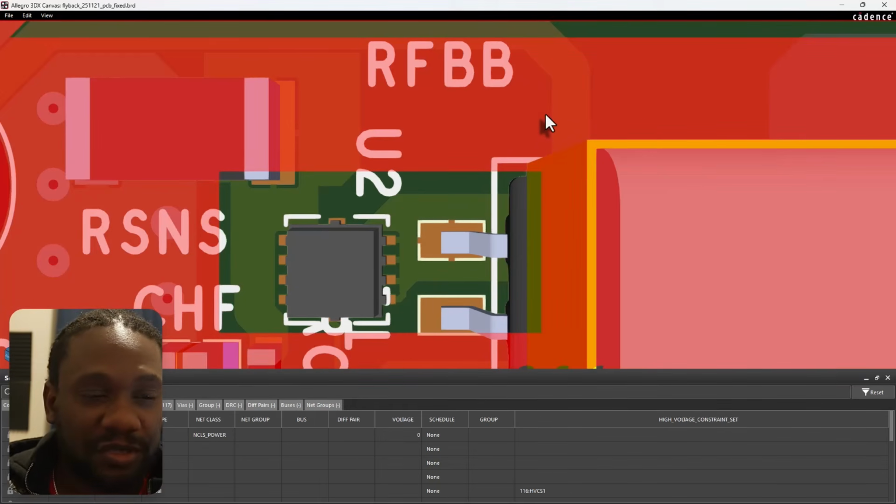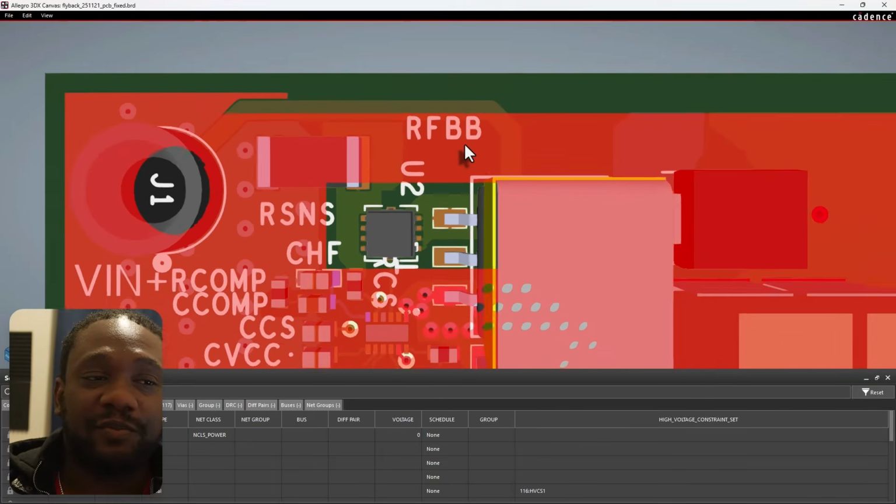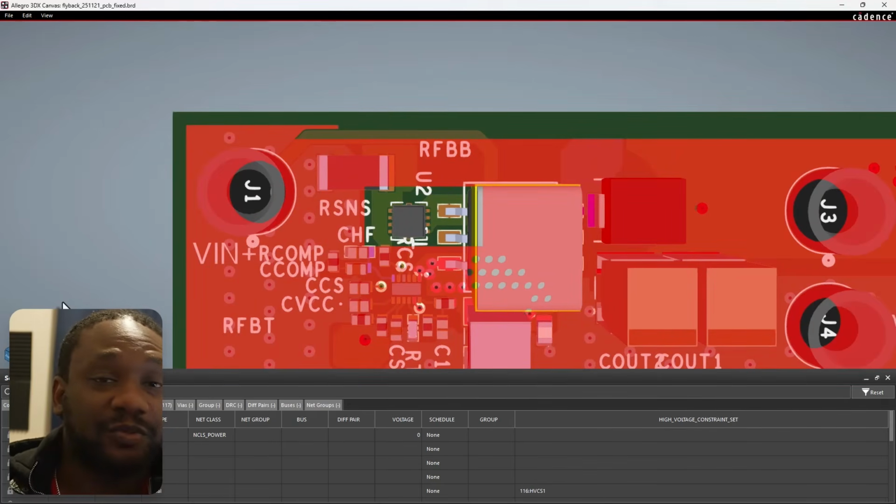So it's a bit nuanced, but it's a doubly effective method when you're playing with inductances and capacitances to lower that impedance. Because the lower impedance, again, is what the field is looking for, not necessarily the shortest distance in space. All right, so just a quick recap. We highlighted the two hot loops. I showed you how I placed the components to shrink those hot loops. I made sure to route and pour the copper close to the hot loop so that they are minimized in size, but lowered in inductance as well.